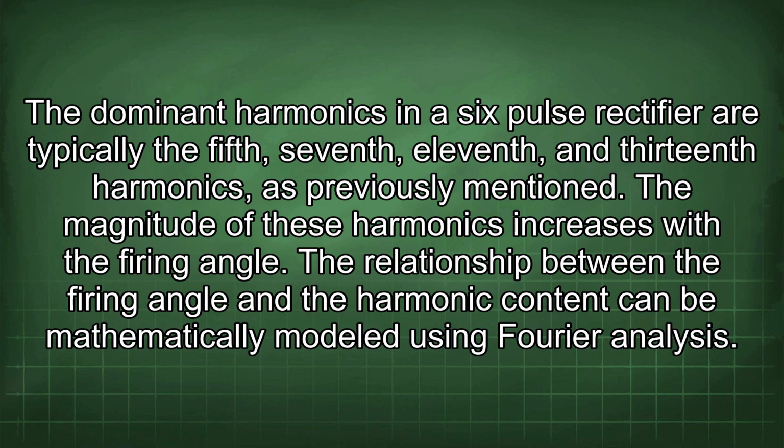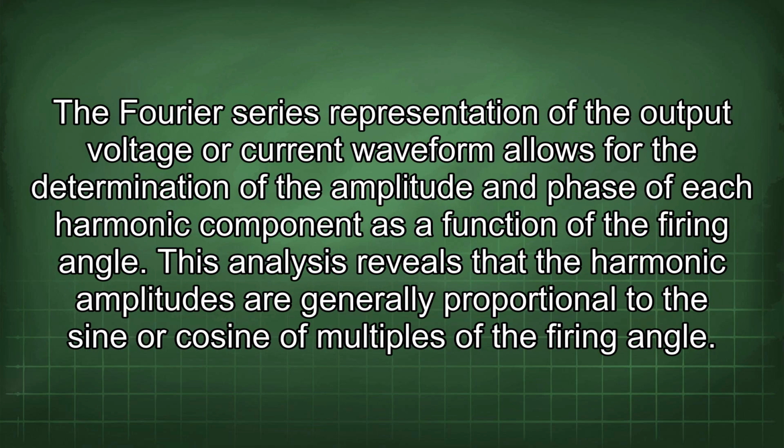The magnitude of these harmonics increases with the firing angle. The relationship between the firing angle and the harmonic content can be mathematically modeled using Fourier analysis. The Fourier series representation of the output voltage or current waveform allows for the determination of the amplitude and phase of each harmonic component as a function of the firing angle.